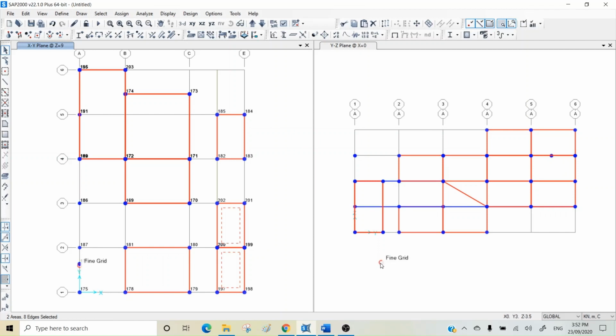And Y doesn't show you any X because I'm in the YZ plan, YZ elevation. If I come here, you can see X 21.5, and if I go very slow, you can see the incremental selection of the grids here. Sometimes that is okay if you need to draw something out of the grid line or out of an element, but an easier way is simply to put a joint with the offset you need and just draw a line between the joints. That would be more accurate.